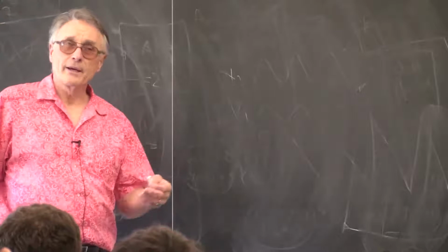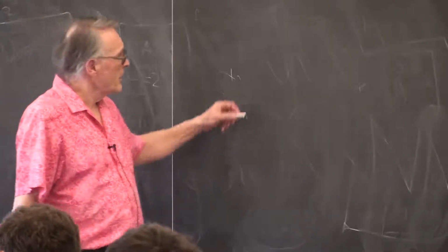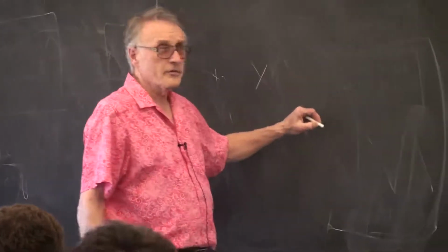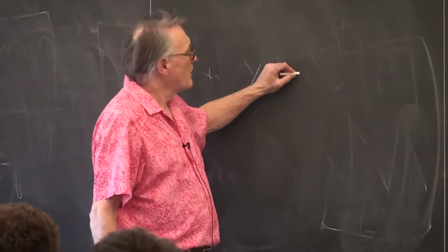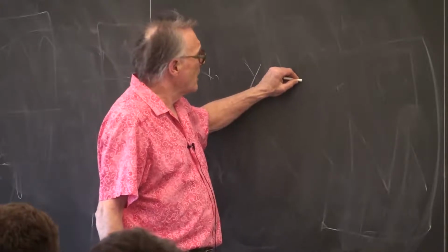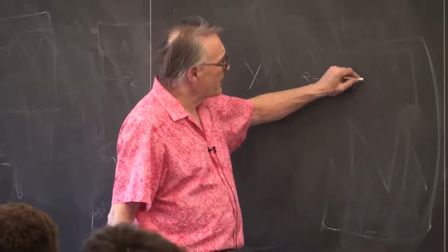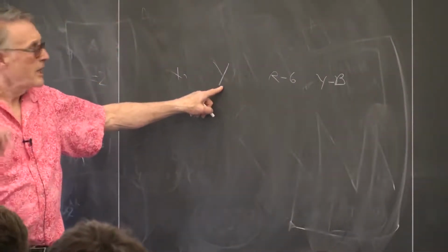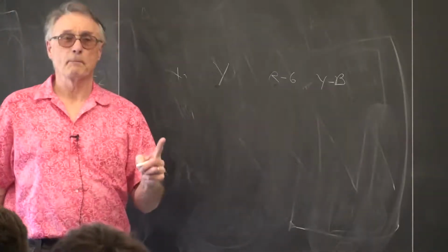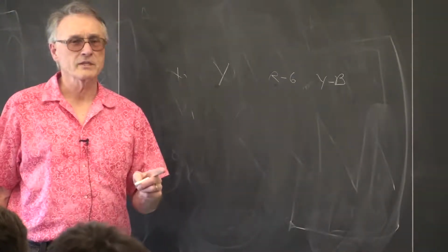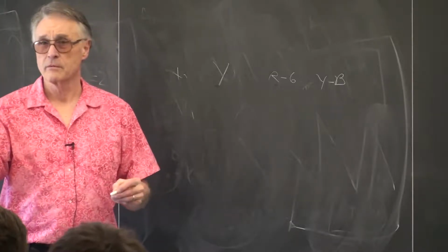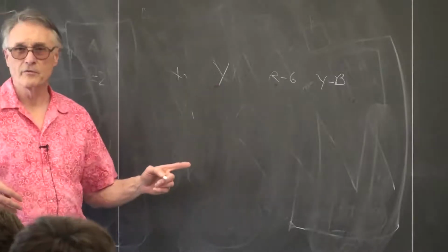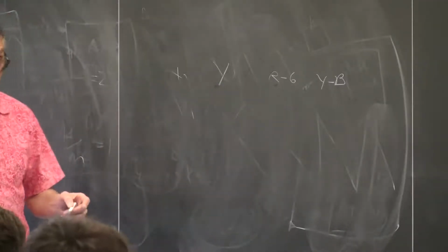And the way the video is encoded coming off the camera, it's actually encoded as an intensity channel, and then two color difference channels, one being more or less red-green, and the other kind being a yellow-blue axis. And so the intensity carries the brightness, and these two carry the spectrum. It's the best spectral estimate you can do with three channels, two spectral components, after you've actually divided out the brightness.